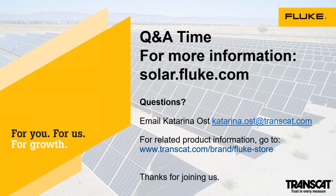We do have acoustical imaging cameras, which is something that you don't see a lot in solar, but they're used a lot on substations to identify arcing. It actually uses an array of microphones, and it picks up certain frequencies and then gives you a visual image very, very similar to a thermal image where it identifies where that acoustical signature is coming from. They're used a lot in process equipment as well. But I think we're going to start to see those used more frequently in solar. We just haven't yet.